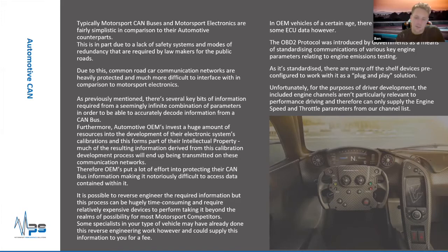If you're say a BMW M3, for example, which is a hugely tuned car in the world, there's many tuners, there's many specialists that may well have deemed it financially viable to spend the time reverse engineering a manufacturer's CAN bus, so that information is readily available for a relatively small cost. So I wouldn't give up on it, but just beware. It's a difficult thing to do, especially if you have no prior experience.